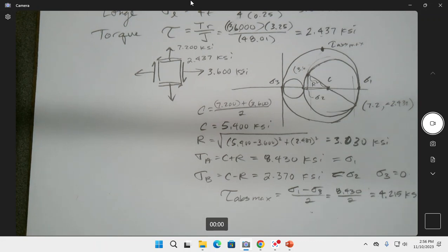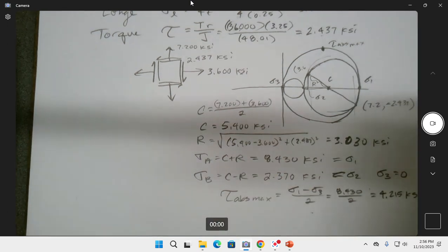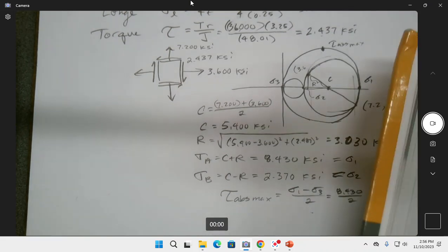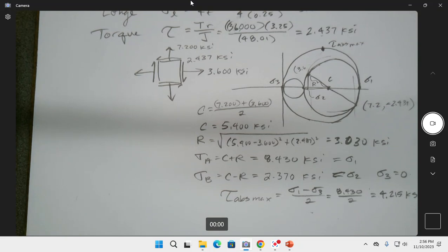So if you want to try to assess this design, these are all very small numbers, but let's go ahead and pick out the weakest thing that we can find in the book. Most of the time, you would want to have a pretty good safety factor for a pipe like this, because you don't know about corrosion and time and loading and surges. This is 600 psi, but what if the source has a big surge? You don't know a bunch of other things that might happen in the future to this. So it's not out of the realm of possibility that you would want a pretty significant safety factor. But let's get the cheapest steel we can get.